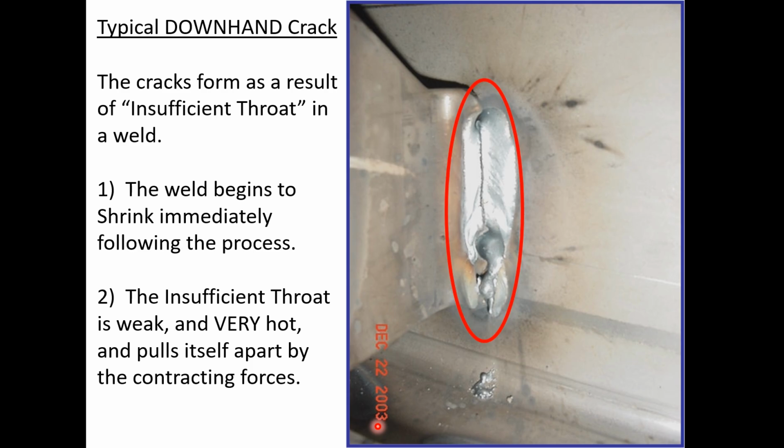So as an example of a downhand crack, now this is happening because the person's going so slow, or they're using too much heat. You have to be careful doing downhand welds. And people, they love downhand welds. I can put in a beautiful weld downhand, but it holds nothing. So downhand welding is almost unheard of in any form of structural welding and professional welding where you hold a ticket.